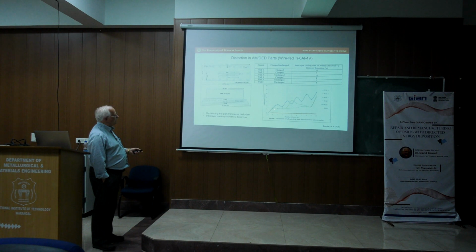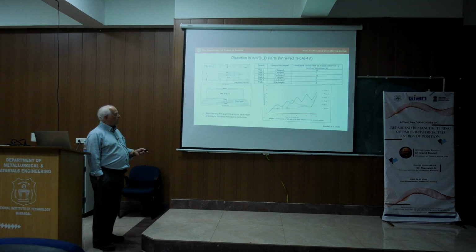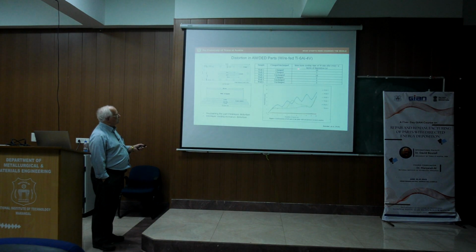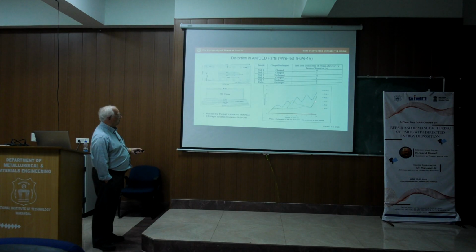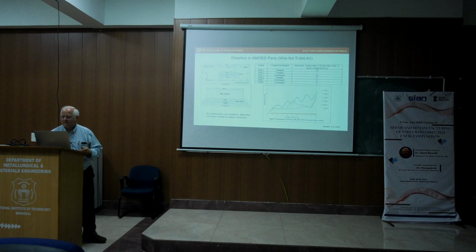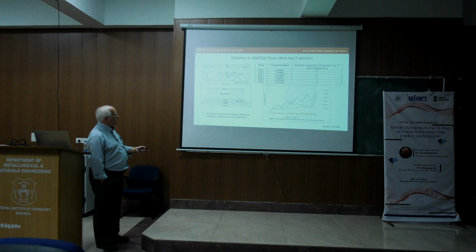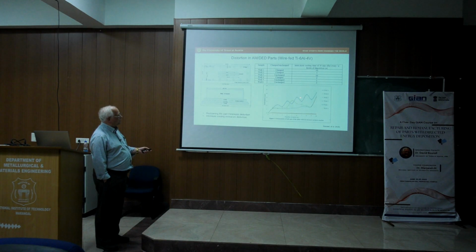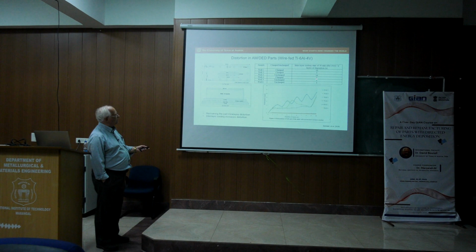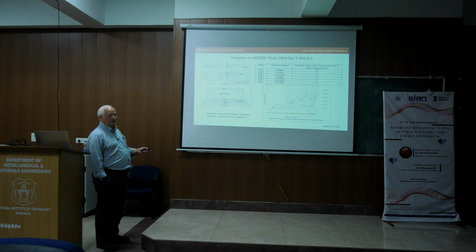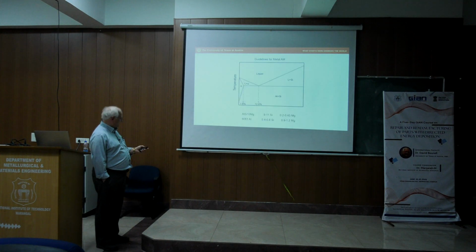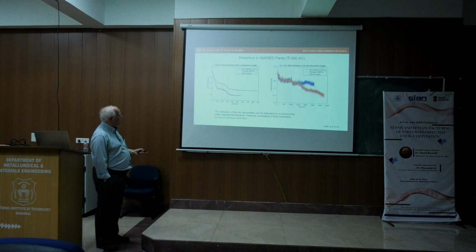So among the unclamped specimens, let's see, did I do it right? The blue one, wall 5, where they paused every 2 layers, has the most distortion.